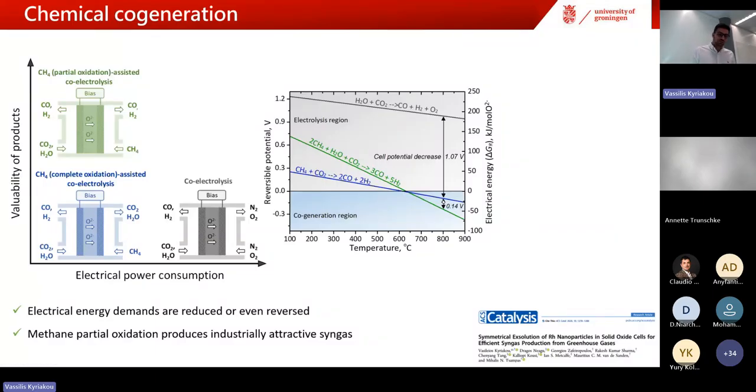How this happens is because the system, and solid oxides are unique systems to do that, can exploit the heat content of your fuel to convert directly to electricity, to electron transport, that helps in the electrolysis of CO2 and the steam. Of course, this is very nice as a concept. We have maybe even power and syngas cogeneration, but you are producing CO2 and water again.